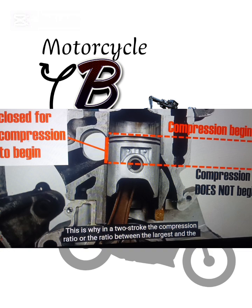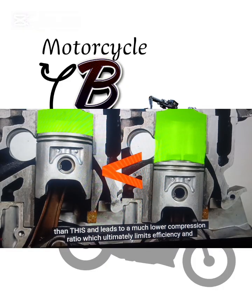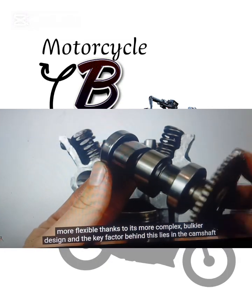This is why in a two-stroke, the compression ratio, or the ratio between the largest and the smallest cylinder volume, is the ratio between this and this volume. Obviously, this is much smaller than this and leads to a much lower compression ratio, which ultimately limits efficiency and performance in a two-stroke engine. The final difference is that the four-stroke is inherently more flexible thanks to its more complex, bulkier design. And the key factor behind this lies in the camshaft.